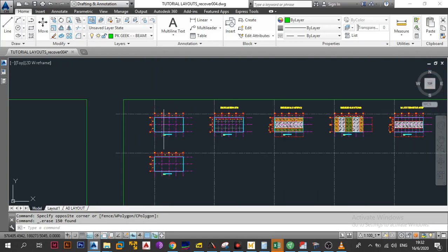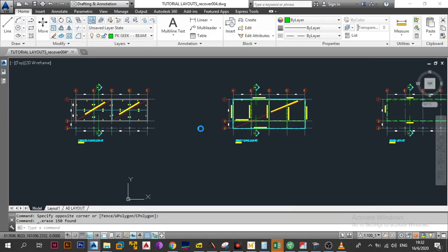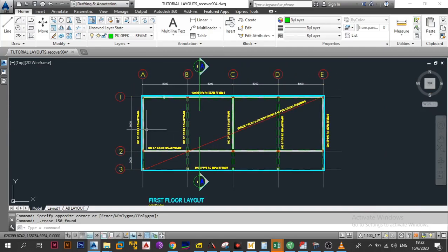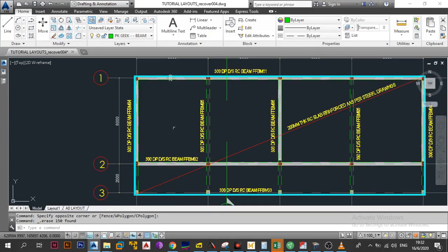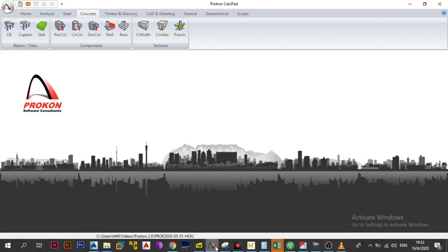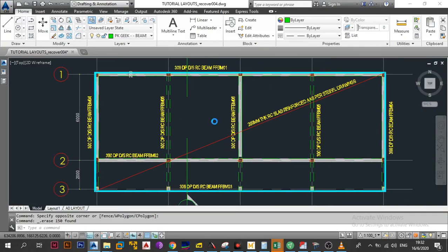So it becomes a bit of a challenge, because when we were designing this other slab, it's quite easy. All you gotta know is how you are doing this. The slab, you can analyze it in any way, or you can just use Prokon. If you go to Prokon, there you have the slab module where you can design the rectangular panel design. For our building, you could have used that one for each of the different panels, and it would have been okay.